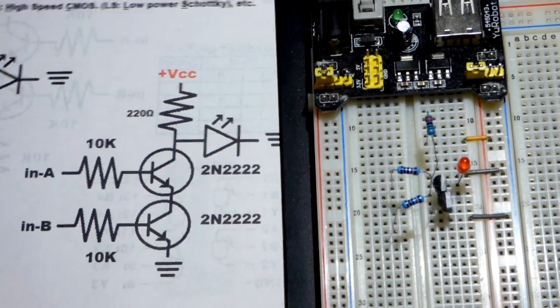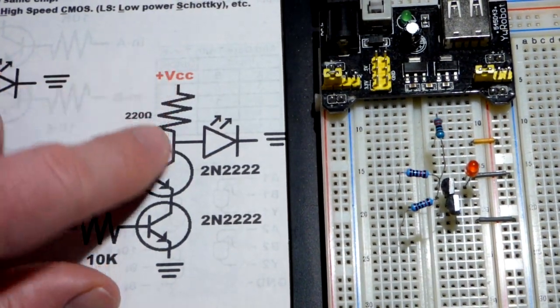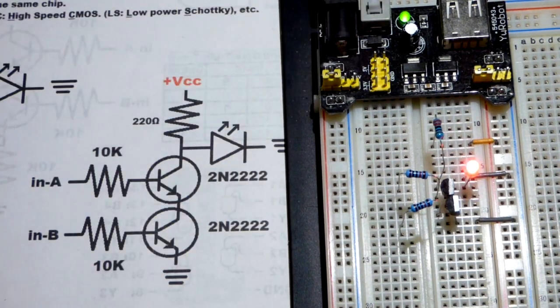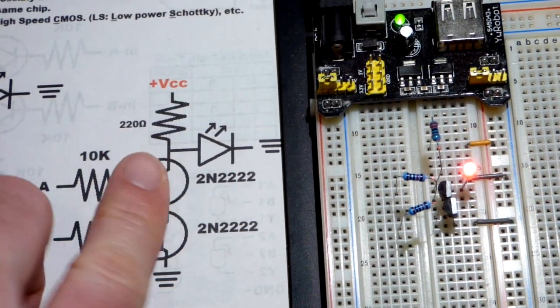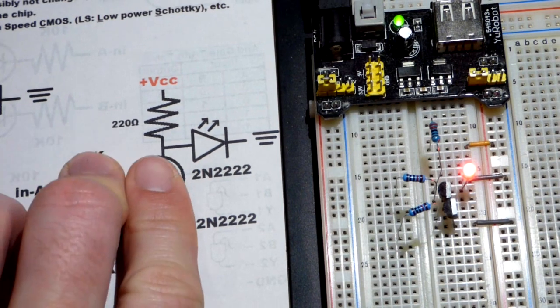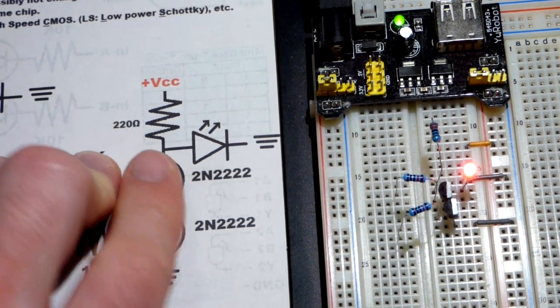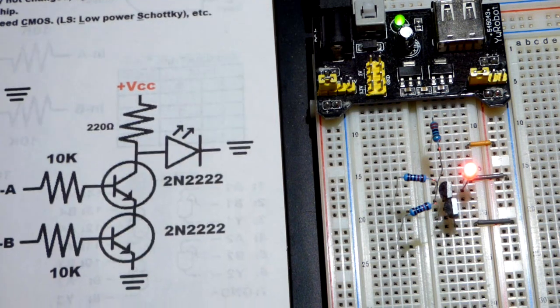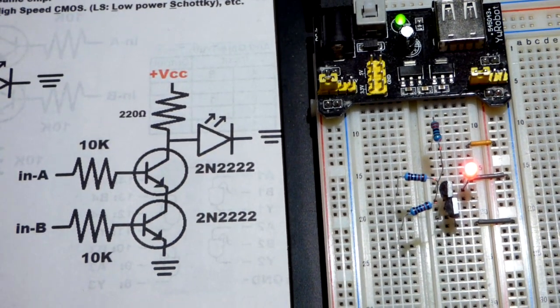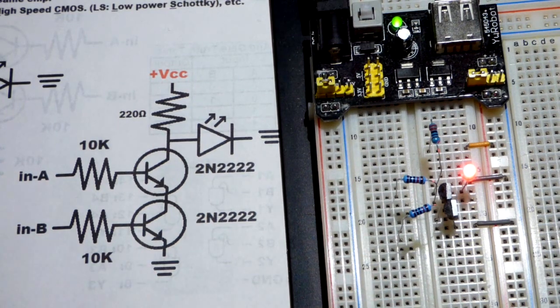And now we have the same situation with the switch, where the LED has a direct path and it is on. Transistors are off. We can basically think of them as not even existing right now. It's just a resistor and an LED because they're not conducting. As far as the electricity is concerned, they don't really exist. They're just insulators, like the plastic on the board.